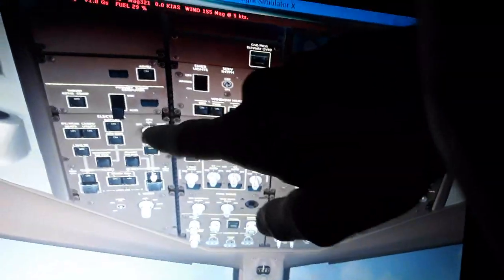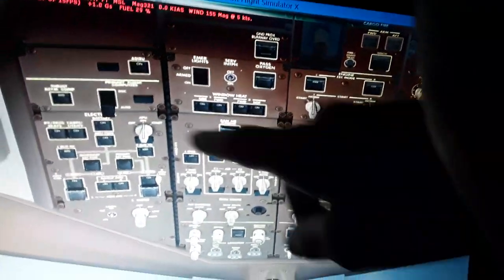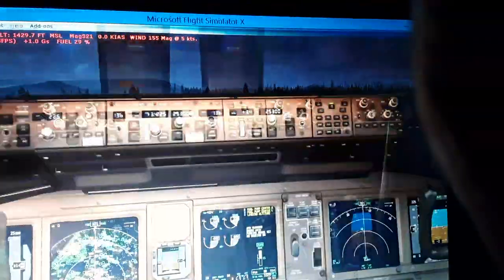We have also the batteries that produce another 28 volts but constant current, direct current, no alternate. We can convert also this into alternate current using other static inverters. So we have the APU also for starting the engines in the ground. This switch that produce electric current, alternate, and also pressurized air for the engine starter when it's pressurized air.